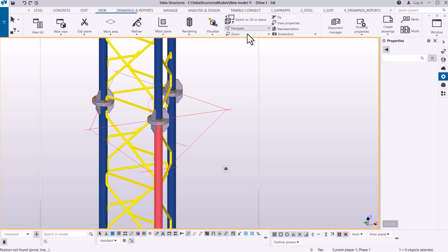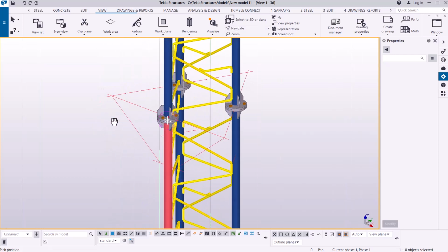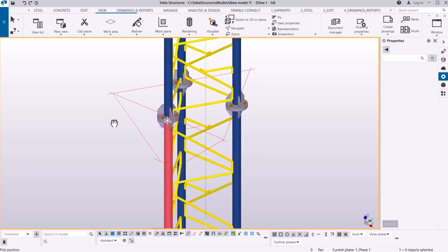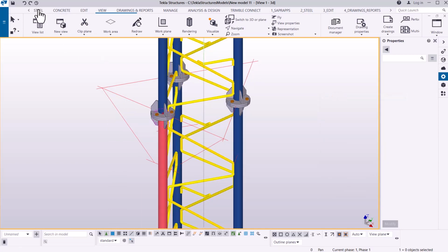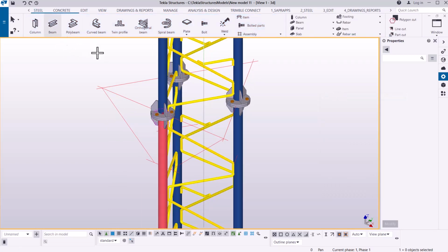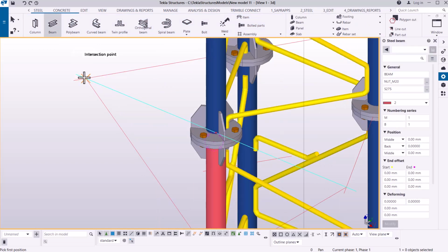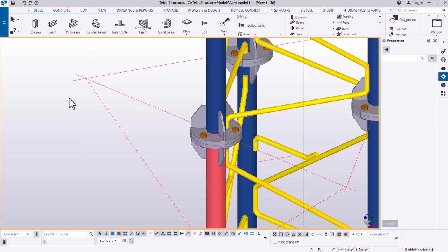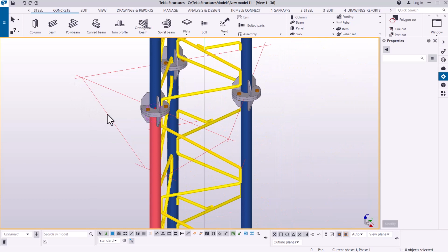So once you have this in place, what we want to do is use these lines for the placement of the fixture, a steel profile. So let me come to steel here, then come to steel beam there, then pick right there. Let me snap on the center there, just to be accurate, because I had already defined the length of these particular lines that matches the length of the steel member. So let me select on it.